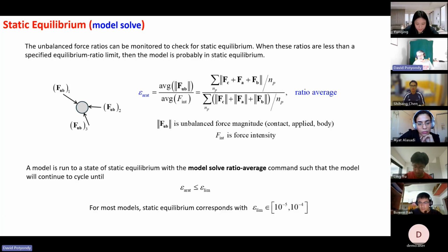And so when you sum things up and you want them to sum to 0 for everything to balance, they're always going to be within what they call floating point precision, which is like 1 × 10^-12 or so. So the velocities will be bouncing back and forth at 1 × 10^-12. Well, that's going to take a huge number of steps, and you don't want to have to look at the screen as you're running PFC models to figure out when to stop.